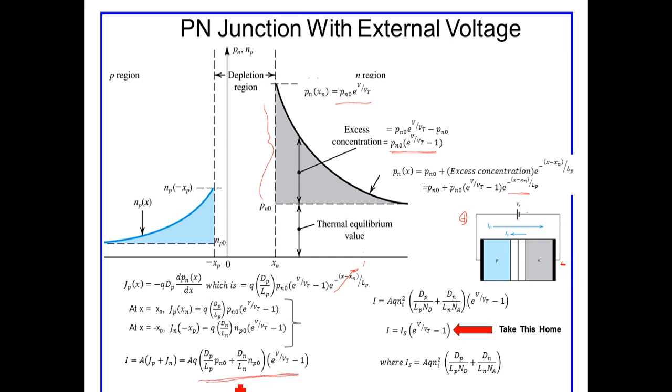And thus, this expression that we come up with here is in fact the expression for the current flowing in this external circuit. But it is I, conventional current I. So even though we know the electrons are going this way, this current expression is the expression for current leaving the positive terminal of the voltage source and flowing into the p-doped end of the diode. To use a little more legacy type of terminology, the electrons then are flowing in through the cathode and the electrons leave the anode.